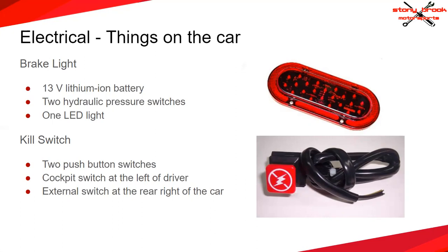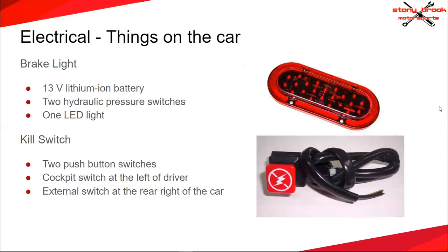The battery is connected to the light through the pressure switches, and in the circuit, the 2 pressure switches are parallel with each other, which means that the brake light will turn on when either one of them is activated. And wires connecting the battery use ring connectors, and wires connecting everything else use spade connectors. By the way, the transponder is part of the composite area.